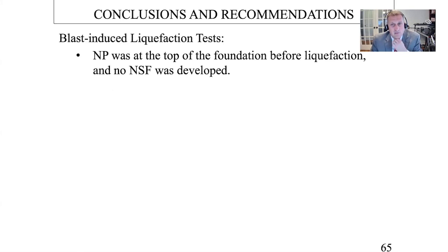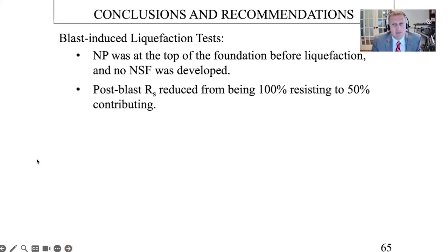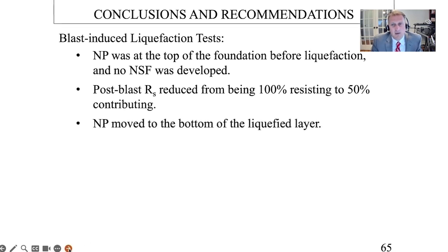From the blast-induced liquefaction testing, the neutral plane moves from being at the top of the foundation before liquefaction to right at the top of the liquefiable layer after liquefaction occurs. Before blasting, no negative skin friction was developed, but after blasting, we do see it. So the reduction in side goes from 100% resisting to 50% contributing, is what we observed. And then the neutral plane moved to the bottom of the liquefied layer.